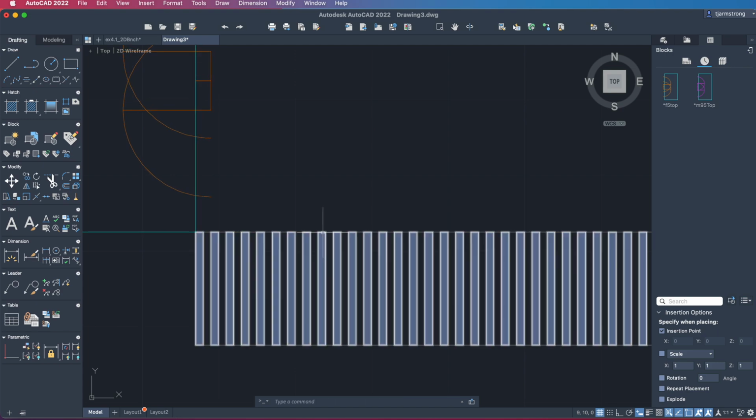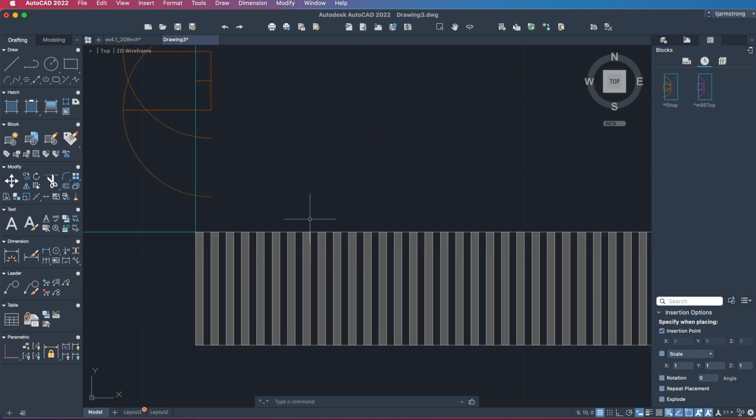Actually, I must have defaulted to rotate, so let me do this again. Make sure I hit escape and start with a blank command window, and I'll type move. Select the move, select the object, return. Select the corner of the bench, and I'll move it horizontally. We'll move it, let's see, we've got to move it 1 meter. 1. And so we just moved it horizontally, so it's got the end of it aligned properly, but now we